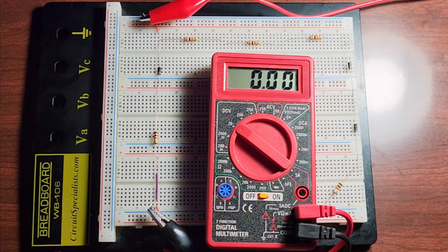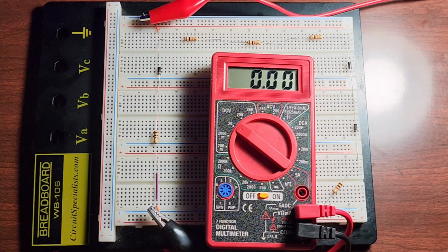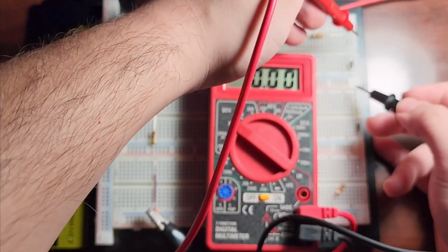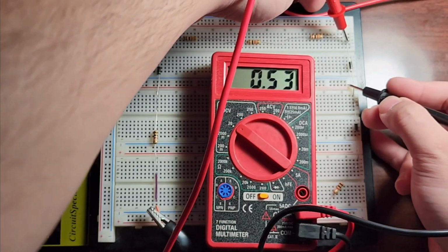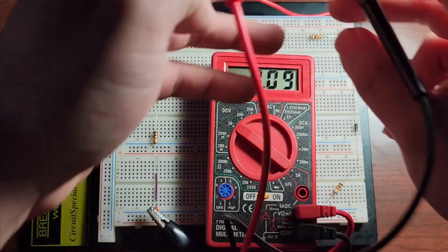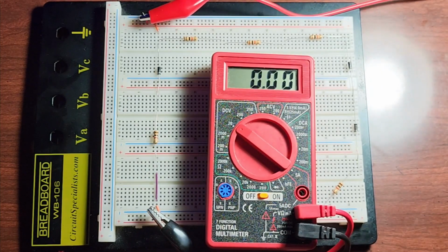So what we'll be using is the 1.4 plus 1/4 (Vn minus 1.4) equation. Now that equation will change a little bit because our Vn is not 1.4 anymore. So anytime you see a 1.4, replace it with, what did I say here? 0.6, right? We saw 0.6. So replace it with about 1.2. So what we'll have is 1.2 plus 1/4 (Vn minus 1.2).